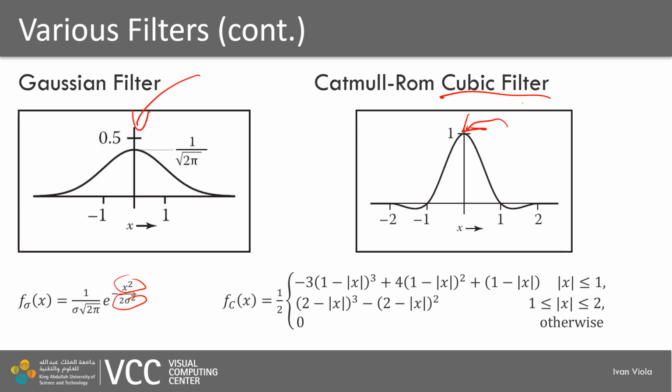I forgot to tell you about the Gaussian filter that in case we trim it, let's say to the extent -1, there will probably be some artifacts coming from this hard trim, so a smooth multiplication with another smoothing filter called a window would probably be more desirable. So we will have such a function which we multiply the Gaussian filter with. That will result in a much smoother transition to 0.